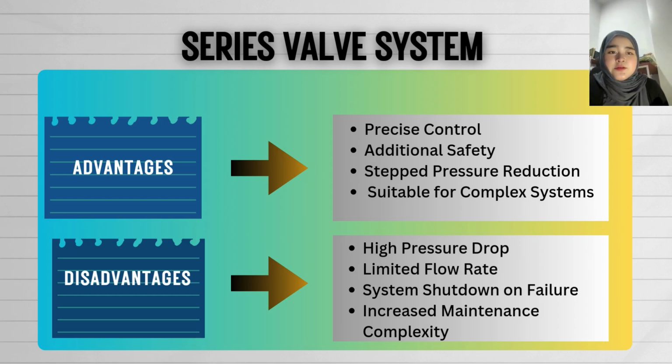And the disadvantages in a series valve system are, the first one is high pressure drop. So the resistance to flow will increase at each valve in series.